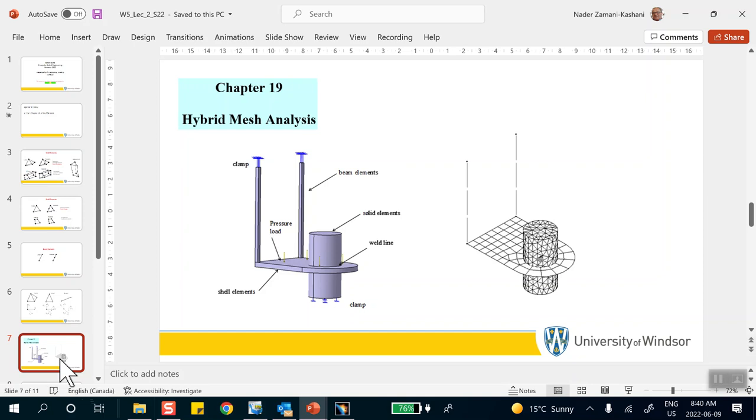That thin, flat part is not a solid, we're going to model it as a sheet with shell elements. You see it over there. And of course, you have something bulky there. Some of you may decide adventurously to model this solid object as a beam. Make sure you do it right. I'm not teaching you that, and I'm going to review it to see whether you did it correctly or not. But you see that you have to model the solid elements. Okay.